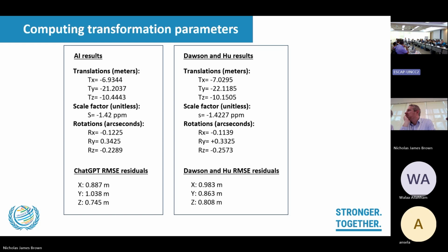Obviously, we live on an ellipsoidal shaped Earth, so any north-south motion does have, in its nature, a change in ellipsoidal height. But even with that 7 centimeters per year north-northeast motion of the Australian continent, the differences were sub-millimeter. So these models are incredibly robust, and I think you can more or less assume that those ellipsoidal heights shouldn't change very much in that third dimension.